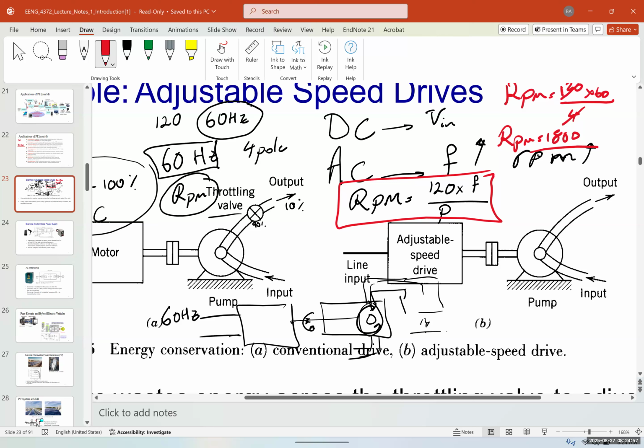If it had 2 poles, then it would be 3600, okay? So the lower the number of poles, it must spin faster, and we have limitations for that. Now, how do they control the rotational speed? They have a valve over here, and by controlling the amount of steam coming in, they could determine the frequency. Depending on the load, they have a sophisticated algorithm to determine when the load is peaking. They don't want to let the frequency drop. When the load peaks, you have a drop in the frequency.